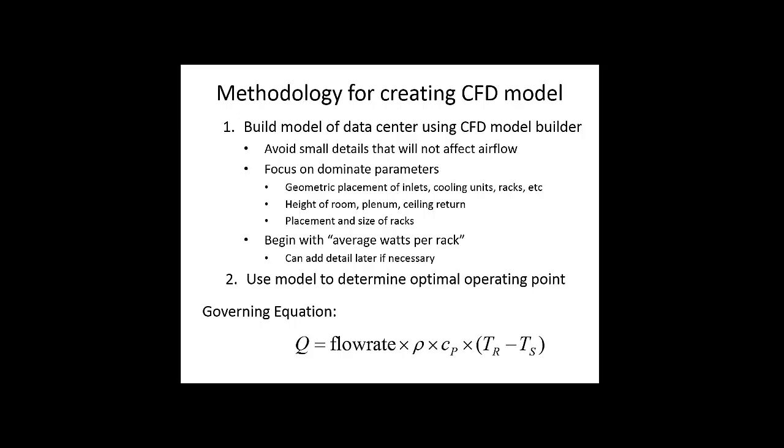And I typically start with average watts per rack. Now, it's not perfect because if it's a 10 kW rack, where's the 10 kW? Is it high? Is it low? You can do that in CoolSim. You can get into the rack and model it all the way down to 1 U of density if you want to. But I recommend you do that